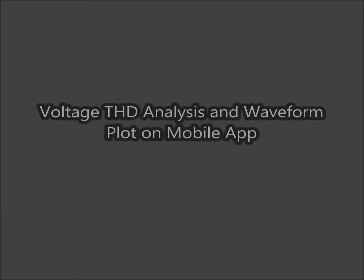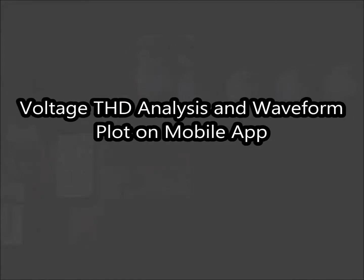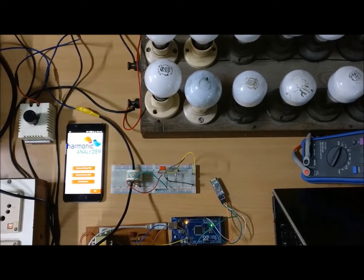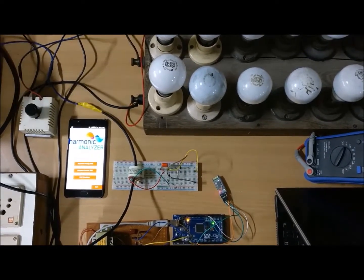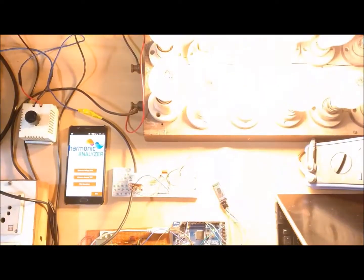Let's have a look at the voltage THD analysis that is done using the hardware setup and observe the waveforms on the mobile app. Now we are going to begin the analysis. First we ensure that the triac is set to minimum, that is the firing angle is set to 0. Now we are going to switch on the lamp load.